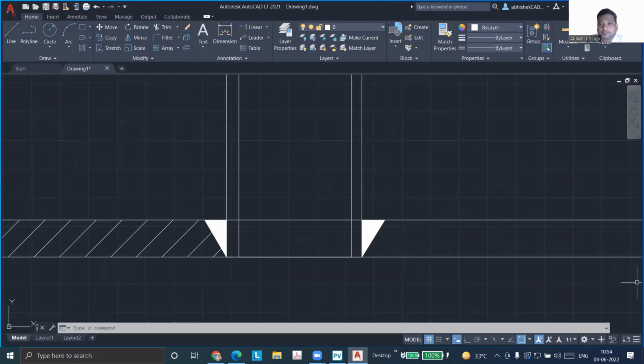UT, sir. Only UT? LPT is performed, but it gives only the surface cracks. Yes. And what about RT? RT cannot be performed here. Yeah, in this case, we'll talk about that. But my question is, if I have to qualify any weld, what we generally do is RT, right? And based on RT,